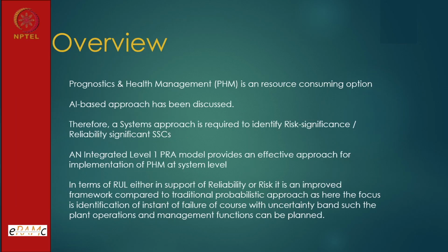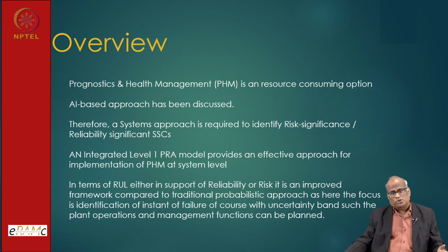So now the overview: we have discussed PHM as a technical module, AI's role over here, and how to build a PHM program. If somebody wants to build one for any mechanical component, dealing with vibration sensing, temperature sensing, all these parameters, you can do it, but you should have instrumentation to give these readings: vibration, temperature, current. Motor current signature is very important, and the oil quality for the bearing is also very important.